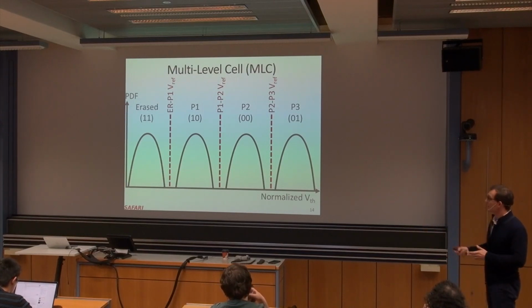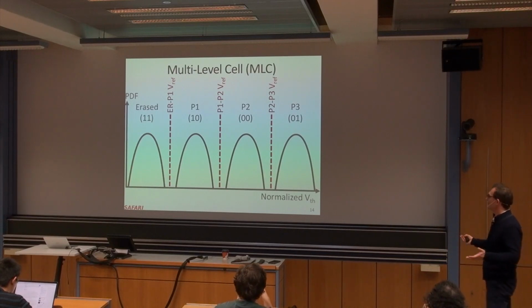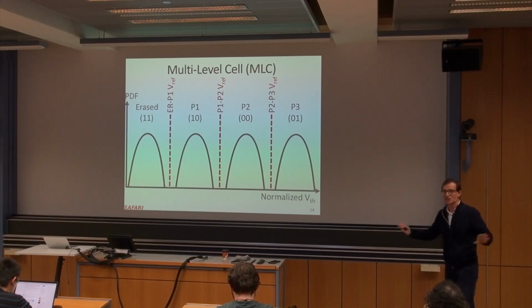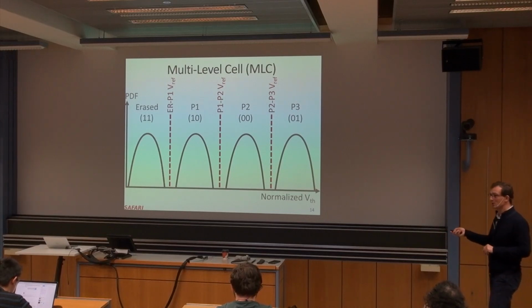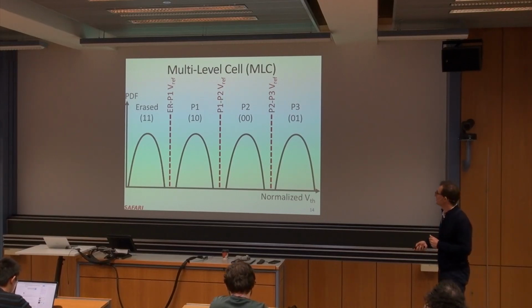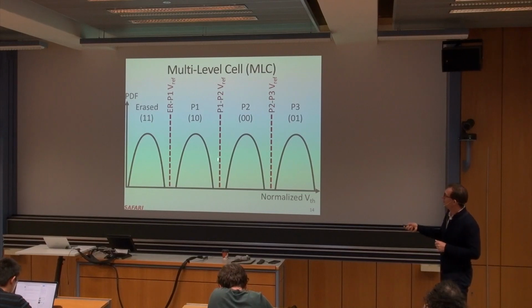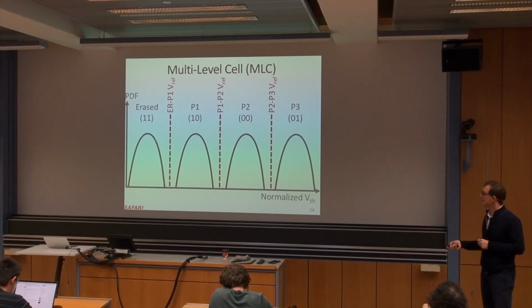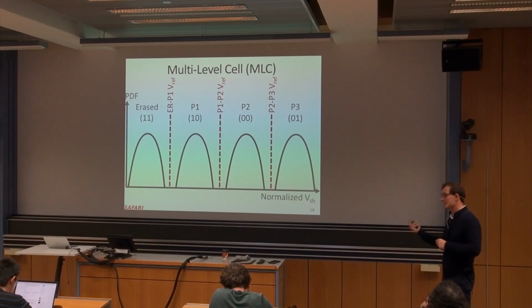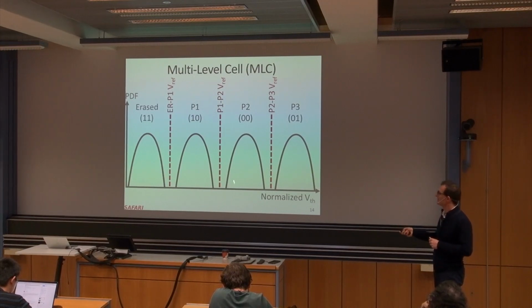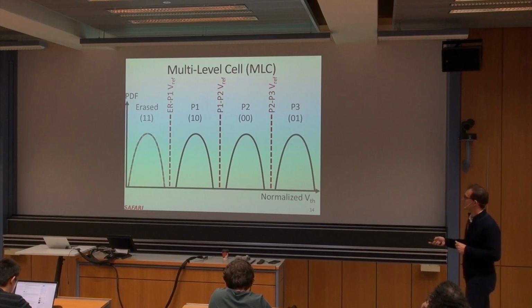Okay, so the upside is you get higher capacity, clearly, with the same threshold voltage range. You didn't change anything in the structure, but you chopped up the threshold voltage range into 4. Higher capacity, you doubled the capacity. But now you need to use 3 different threshold voltages to identify a cell's value. And the other downside is your reliability may have reduced because your distribution may not be as nice. The distribution may actually span partly these threshold voltages.